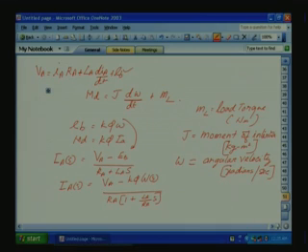Okay. Now omega(s) is equal to MD minus ML divided by Js. This also we can write, MD is equal to K phi into IA.